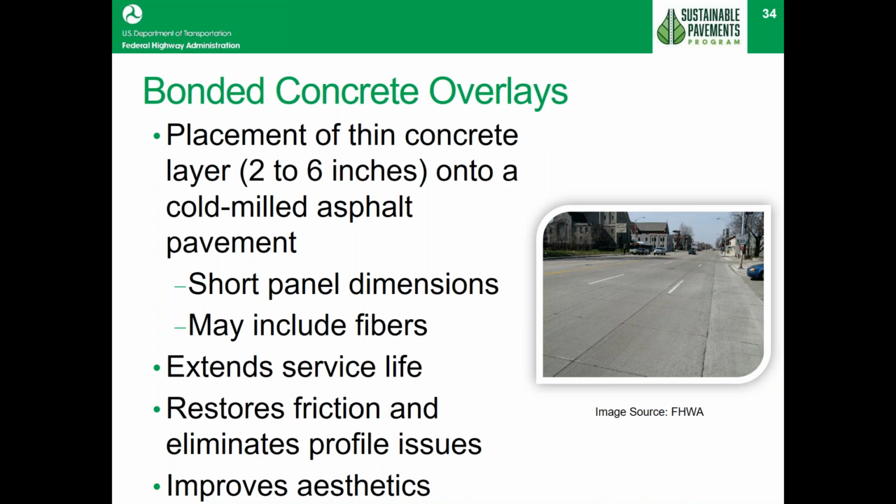Now we talk a little bit about bonded concrete overlays in here. You may not have seen these used too frequently in your location, but they do have some use for special situations, such as where asphalt pavement is not holding up. For example, you may have some areas where the pavement is shoving because of trucks turning on a curve or something like that. Some places you have extreme rutting, and it's very difficult to control.